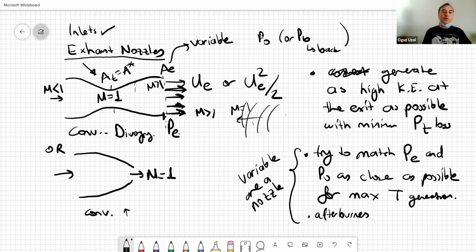Okay, of course that helps, especially for fighter aircraft, if they want to do some strange or crazy maneuvers. Of course that helps, because during those strange, crazy maneuvers, wings will stall actually. So there will be no lift generation on the wings. There will be no airflow around the wings. At those instances, thrust vectoring provides the lift as well. Okay. Normally we don't do that.